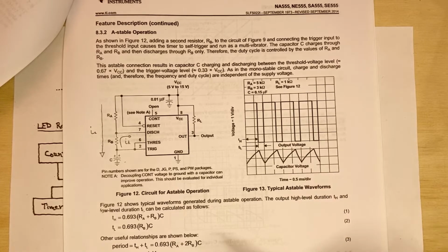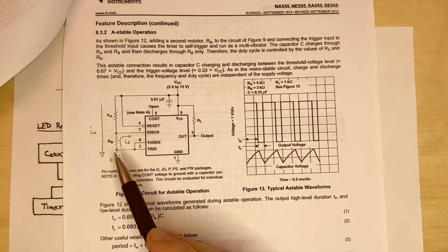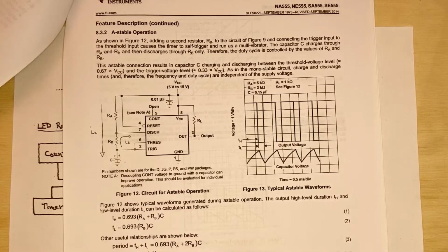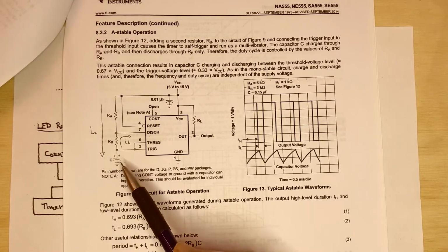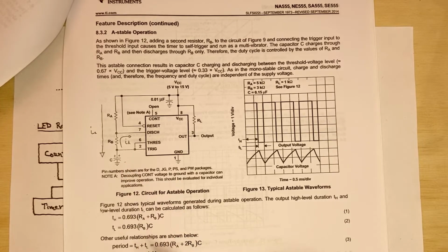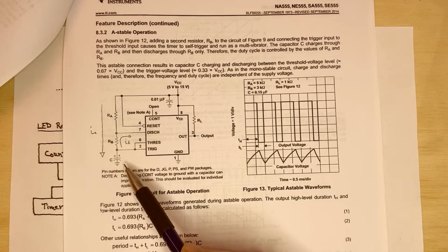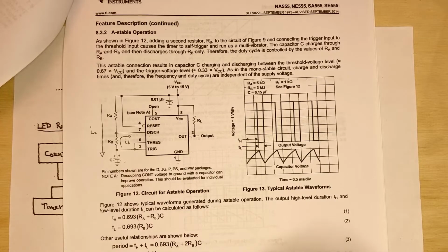Now, it's no coincidence that the components that we need to add to this chip are a resistor and a capacitor. And this is because a resistor multiplied by a capacitor equals time. So ohms times farads equals seconds. And this is an exceptionally useful phenomenon. This means that with these two dirt cheap components, we can essentially have like a little stopwatch for our electronic circuits.